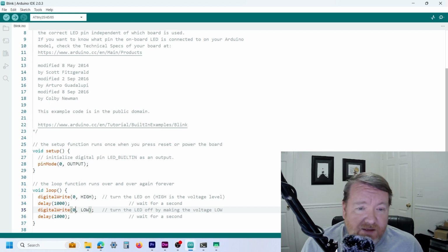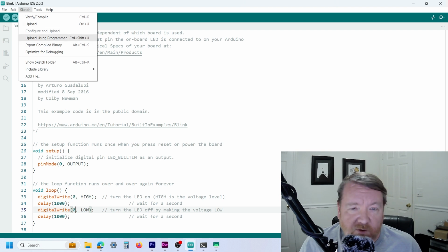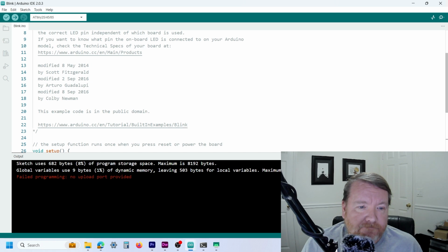Okay, so we've now done all that. The final thing to do is upload this blink sketch. Now don't go to upload like you normally do, just go beneath it, upload using a programmer, and click that.